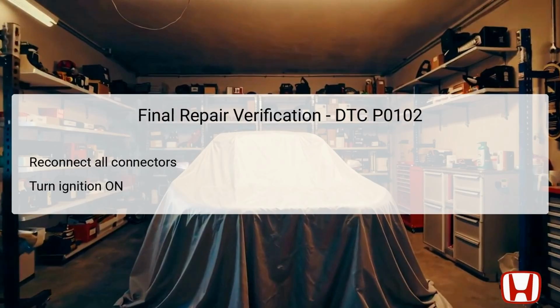To ensure that all repairs and replacements have been successfully implemented, begin by turning the ignition to the lock position, 0, and reconnecting all relevant connectors. This step is vital to ensure that the electrical circuits are complete and can facilitate normal function. Proceed by turning the ignition switch to the on position, 2, once again. Use the HDS to reset the engine control module, ECM, and perform the ECM idle learn procedure. After that, check for any pending or confirmed DTCs.